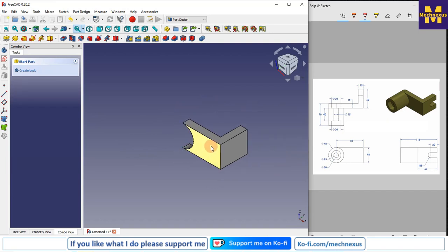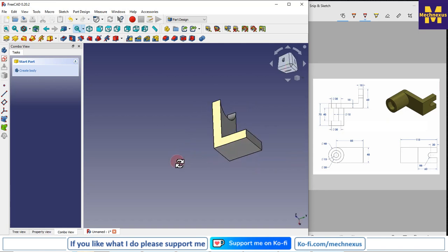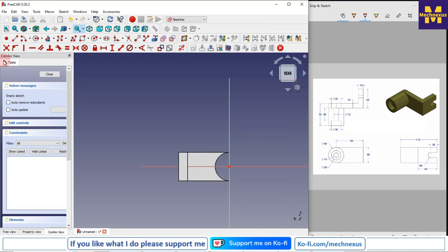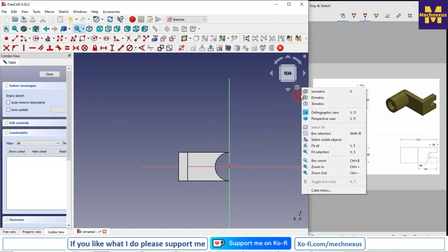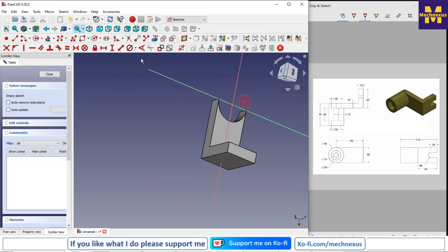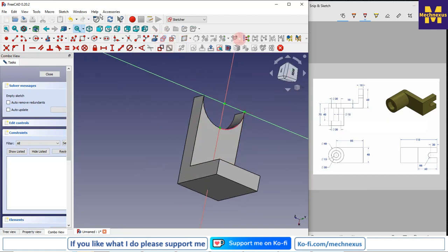Now I will select this face and I will create a sketch, and I will switch to the isometric, and now I will project my geometry, and I will draw a circle here.